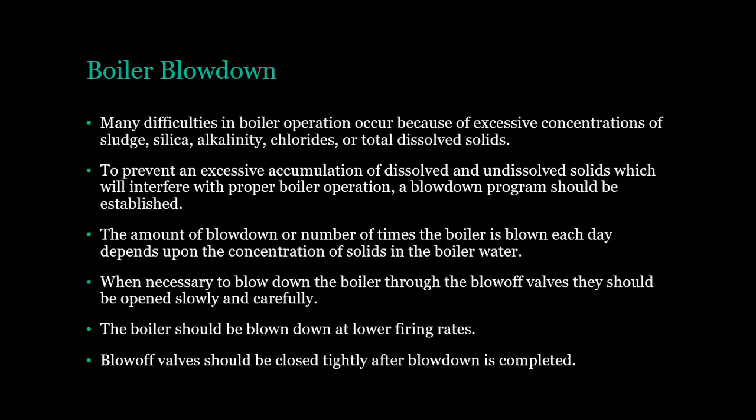When necessary to blow down the boiler through the blow-off valves, they should be opened slowly and carefully. The boiler should be blown down at lower firing rates. Blow-off valves should be closed tightly after blowdown is completed.